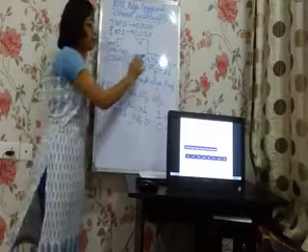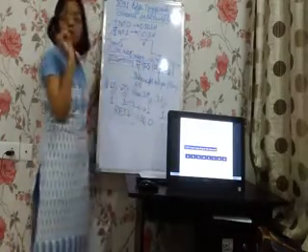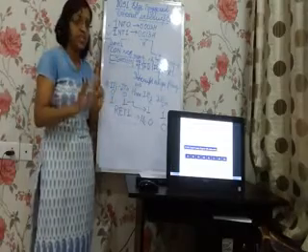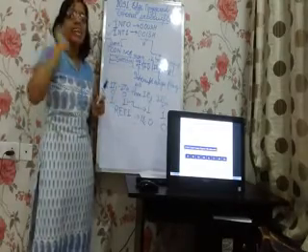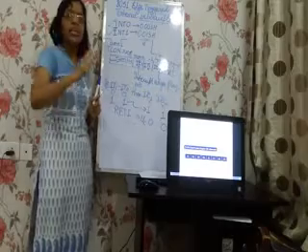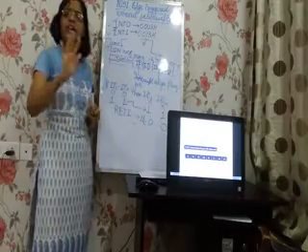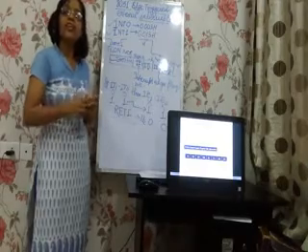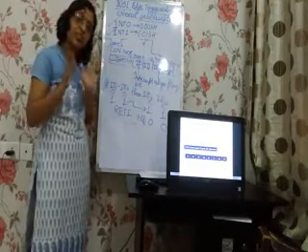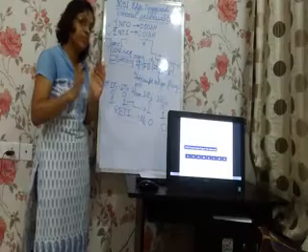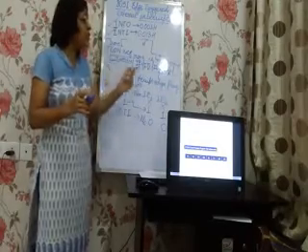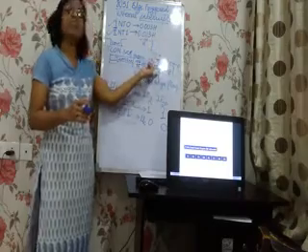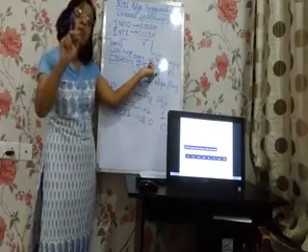Just remember, IT1, IT0 are only for informing whether the interrupt is defined as level triggered or edge triggered. When IT1, IT0 are 0, 0, IE1, IE0 are don't care, because the interrupts are not defined as edge triggered interrupts. They are defined as level triggered interrupts. Only and only when IT1, IT0 are 1, 1, the status in IE1 and IE0 is said to be a valid status.